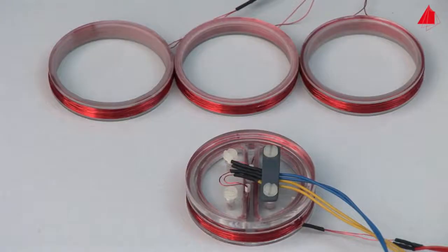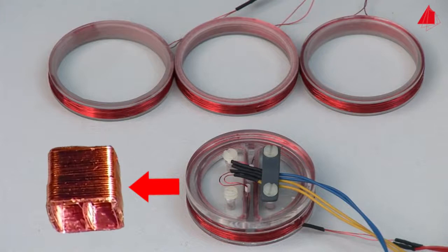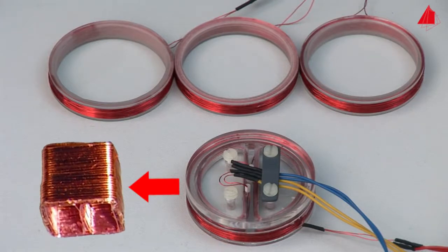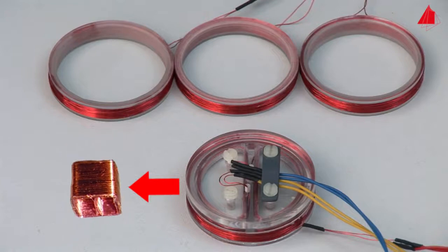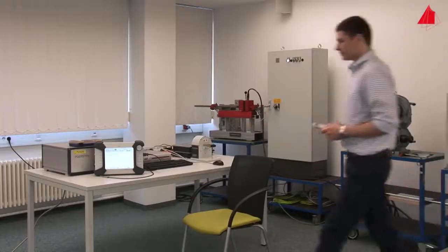To demonstrate the basic principle, we have chosen rather large coils so far. However, the disadvantage of large coils is that only large defects, such as our rough saw cuts, can be detected. In practice, mostly very small coils are used, as shown in the example on the left-hand side. In this way, also small defects can be detected. The coils don't have to be round or D-shaped, but can also have a rectangular cross-section. Now let's take a look at the examination of a component in practice.